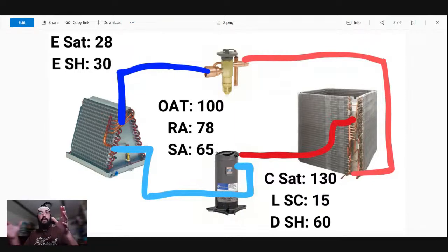We've got a fairly condensed line set here in this made up example. There wasn't any severe loss across the liquid line, which would also help us indicate that we don't have a kink in the liquid line, because if we had one, I would have expected a more dramatic temperature loss from condenser to TXV.